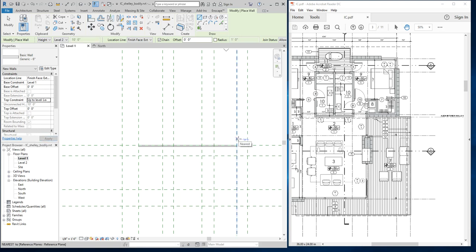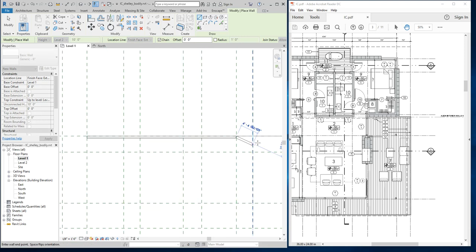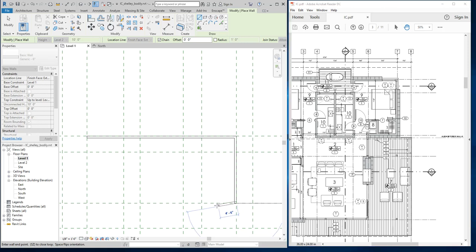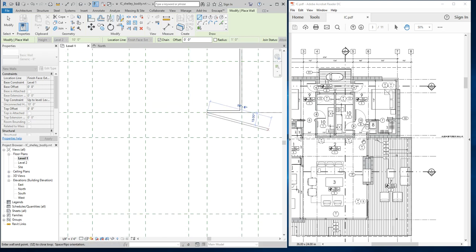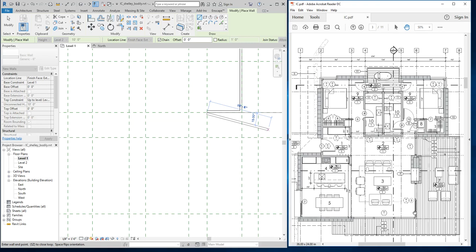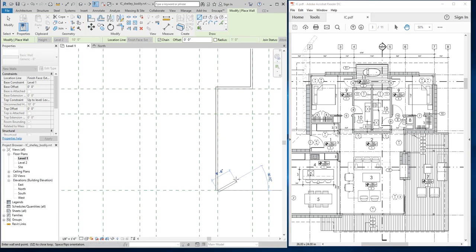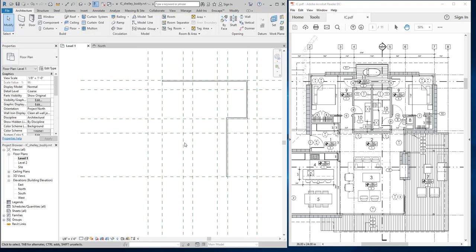So this is going to go from this grid line here. And you see how that little piece of wall overlaps. That's okay. In Revit, those will join together automatically, and it will be a nice, neat little corner. So down two grid lines to right there. Click. And then it comes down to there, and it goes over to grid line 6. So I'm going to pop over here to grid line 6. Click. I'm going to pan and move down, and we go from grid line C all the way down to our last grid line, which is E. So this proceeds down all the way to the very end. Click. Escape. Looks pretty good. We didn't get quite all of the elements, but that's okay for now.